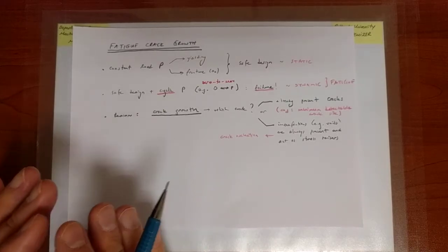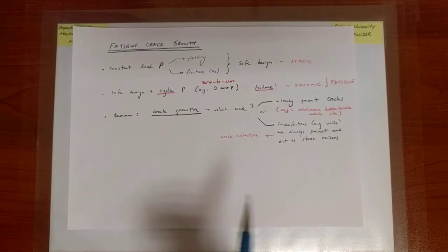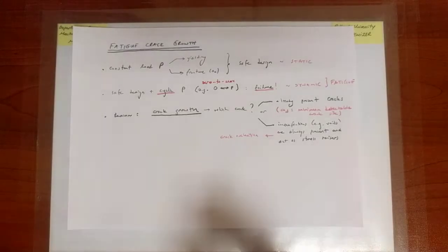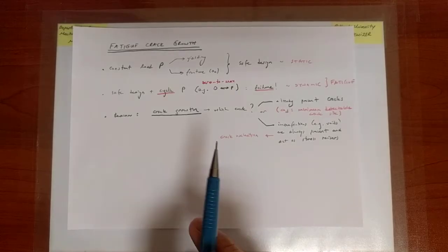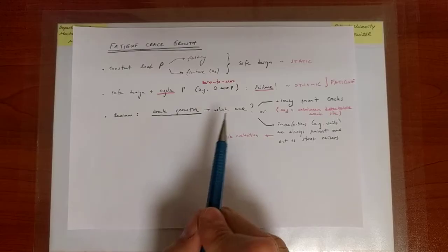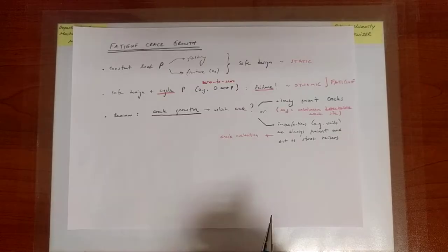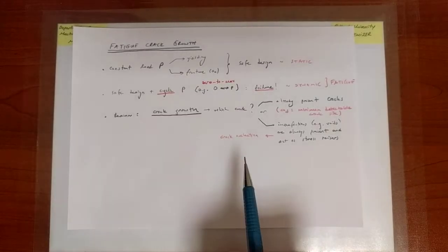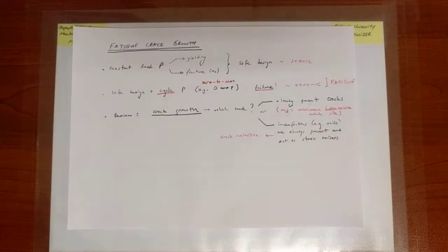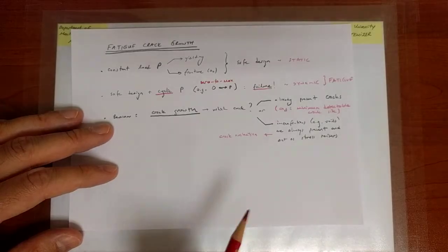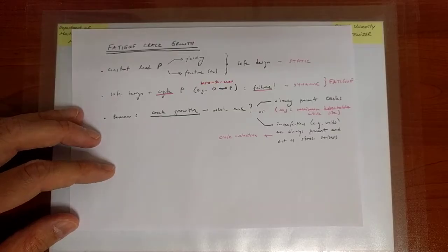So remember, even the beginning of fracture was highly mathematical. We were able to write down the stress field in the vicinity of the crack tip, and based on that we actually formulated a failure criterion through the stress intensity factor. As we move more and more into the region of cyclic loading, into fatigue, we're going to start working with more and more empirical relations. In other words, relations that do not necessarily rely on nice theories like elasticity, but rather heavily on experimental data. So just keep that in mind, that fatigue is quite empirical.